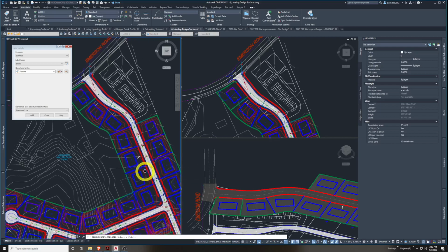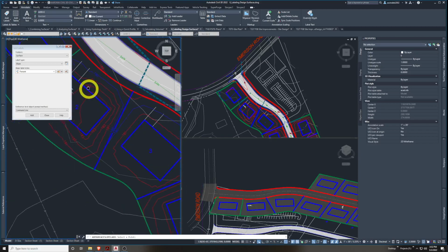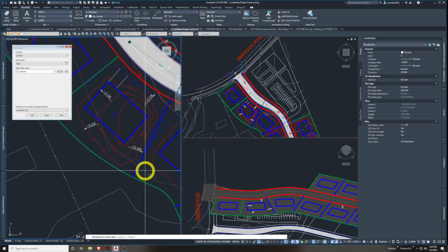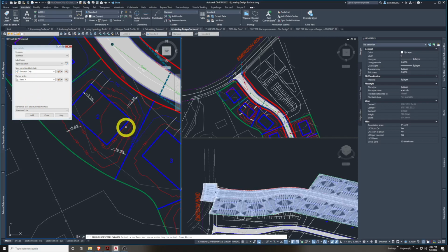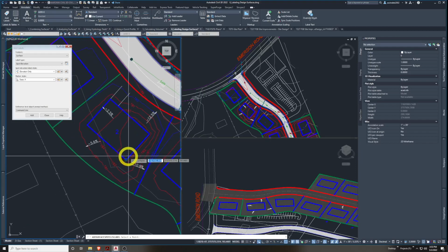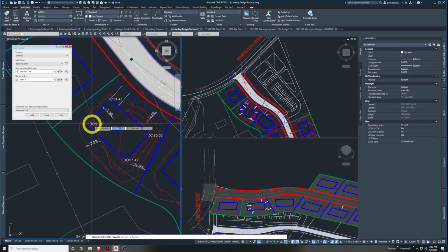And let's just start going to the front yard of lot 2 here. We'll put some labels at the slope, generally in percentage. Add a few, that's fine. Hit escape again. And now we'll add some spot elevation labels. Let's just do spot elevation. Elevation only is fine. And let's pick add again. And we'll pick the same surface we've been adding to. In this case, let's pick the 4 corners of the building pad that we've been kind of doing. I kind of missed that one. We have 4 spot elevations.